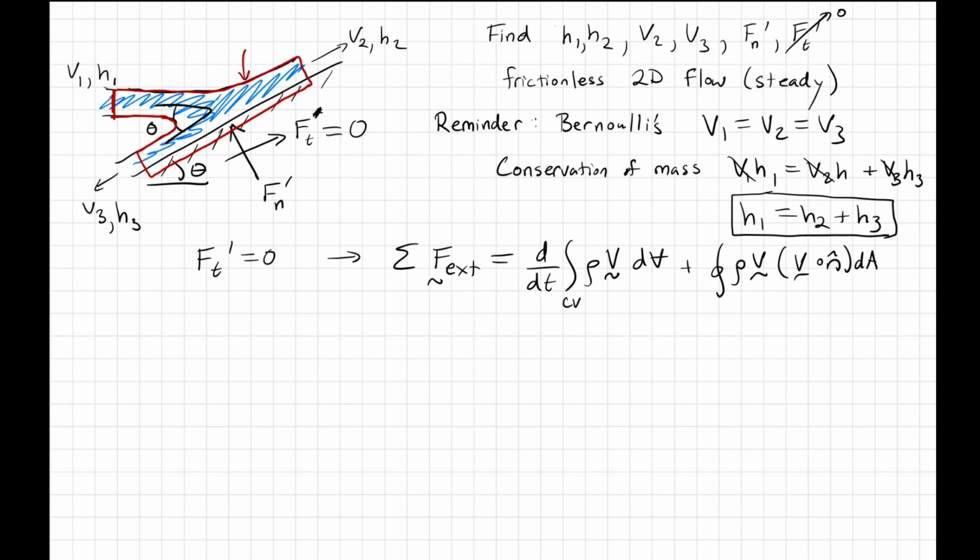And I'm going to say that all faces of this are fixed. So if I have a fixed control volume, the control volume doesn't move with the fluid, it's just fixed in space, then I'll comment on a couple things here. You'll notice I did not write out reduced velocity, and that's because I intended to use a fixed control volume. If I didn't, I would need to use the relative velocity between the fluid and the control volume. But because I have a fixed one, the control volume doesn't move.